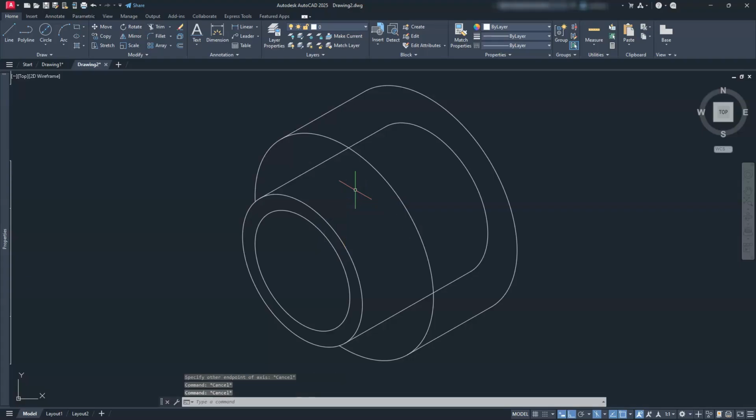Oh, I forgot to hit I, enter. That's what I was missing. EL, enter, I, enter. There we go. I'm just going to go to this center. Type in D, enter, and then this is my 55, right? So this is where that portion kind of comes out, right?